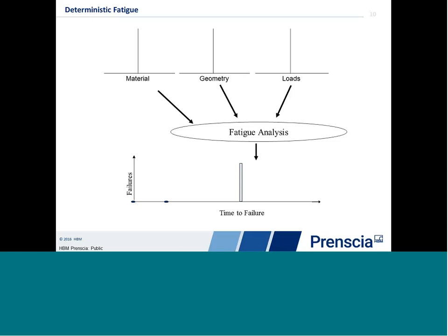That gives us ideas about maybe the central tendency of life, but realistically, we know there's actually a probabilistic side of this we need to think about. There's actually a PDF or probability density function that probably describes material strength. Not every part that's produced out of a certain material will have the same characteristic strength. Likewise, in geometry, every print that we produce says that the nominal thickness of this part or the nominal dimension is this, with some tolerance.